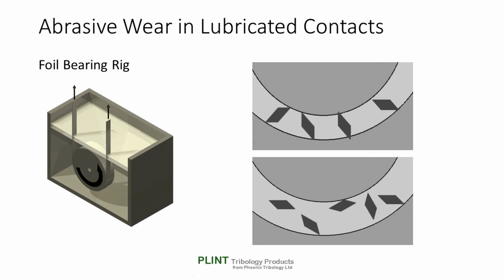Journal bearings, except during startup, are essentially designed to operate with comparatively thick lubricant films between the loaded surfaces. Transit of particulate contaminants through the bearing gap can give rise to different wear mechanisms, each producing different wear rates. When the size gap ratio is small, worn surfaces may consist of a large number of small pits and indentations, usually with no obvious orientation in the direction of relative sliding, indicating either free movement of particles through the fluid film and subsequent impact with the surfaces, or the rolling of lightly loaded particles through the contact. In both cases, the actual load on the bearing is of no relevance other than as a mechanism for setting the bearing gap.